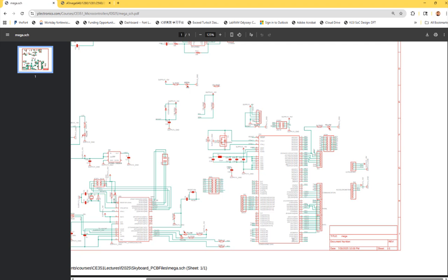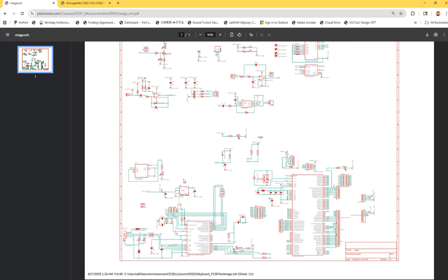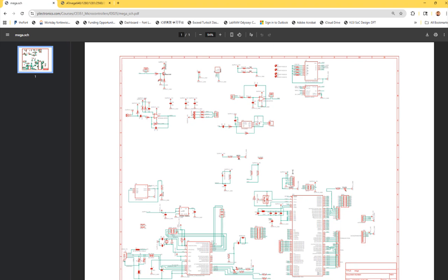And this chip is a USB to UART converter, that serial chip, and we don't need it. So all these components over here can be removed. We're still using USB to power it because that's a requirement of the project. So we're still using the same cable to power it up. You need to keep this port over here and use the 5 volts just as the power supply, not for communication or data purposes. So still keep this 5 volts, and you have this microcontroller, and you have the SD card.